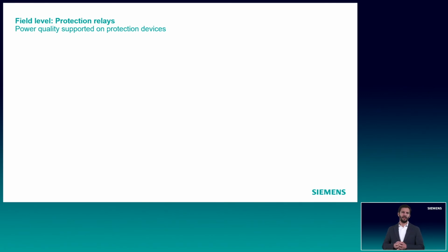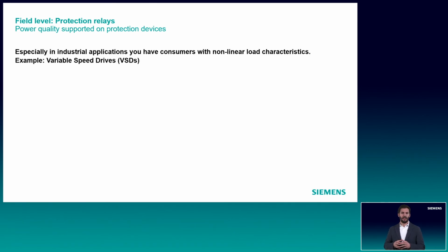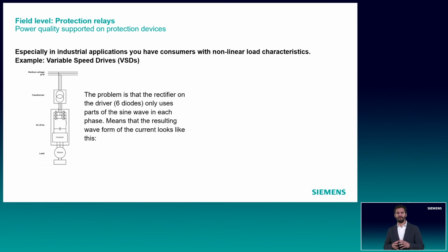Talking about power quality in industrial plants, you will find very often motors that are speed controlled. Based on our experience, variable speed drives are the largest possible source of harmonic generation. Modern speed drives use a rectifier to create DC voltage. This DC voltage feeds an inverter that can generate variable frequencies. According to the generated frequency, an asynchronous motor turns.